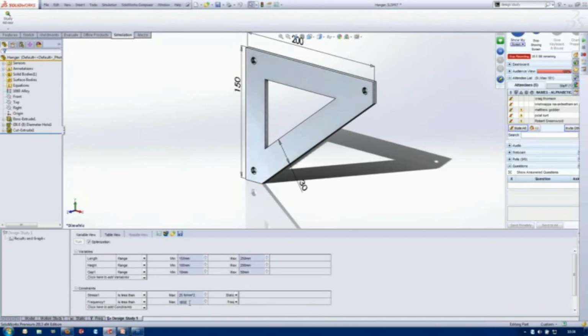So if this was a desk bracket or wall bracket and you've got computer equipment on it, for example, you've got a whole lot of fans and things that will be spinning at that speed. I happen to know, because I previously checked the results, that 1600 is between mode shapes 4 and 5. Hence why I picked my frequency of step 4 to be between those two.